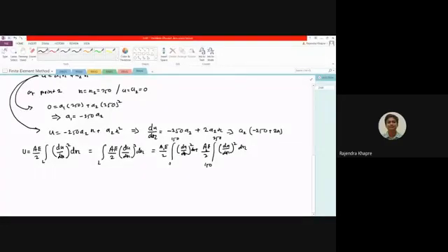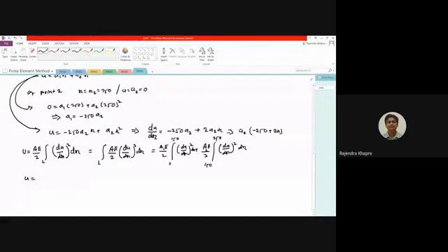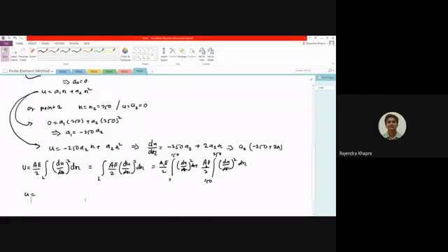So if you have a varying cross-section area, in that case you have to break the limits into 2 parts or maybe 3 parts depending on the type of the problem. If it is a varying cross-section area, you go for A1 and A2. If it is a varying modulus of elasticity, in that case you may have to go for E1 and E2 also. In this particular way, now you have to analyze the problem. So you can have the U value as, let us say, AE divided by 2. I'm assuming the value of A is not given over here.